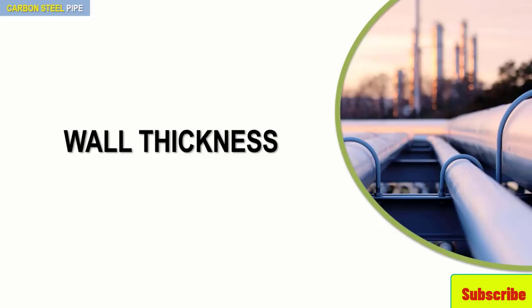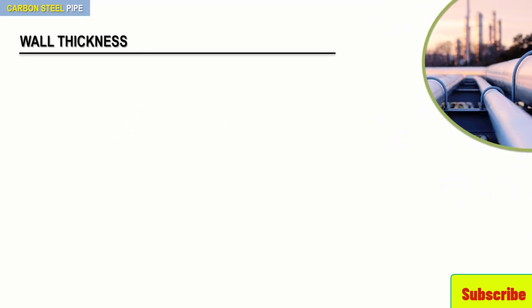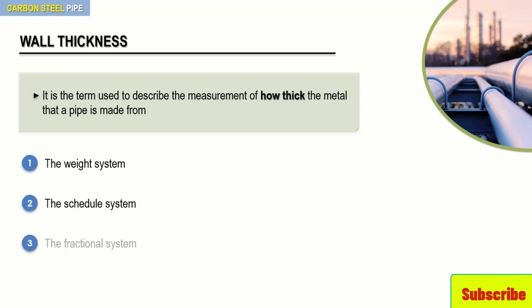In this video, we're going to introduce you to the concept of pipe wall thickness. So let's have a closer look. Wall thickness is the term used to describe the measurement of how thick the metal is that a pipe is made from. There are actually three systems in which a pipe's wall thickness can be categorized. These are the weight system, the schedule system, and the fractional system.